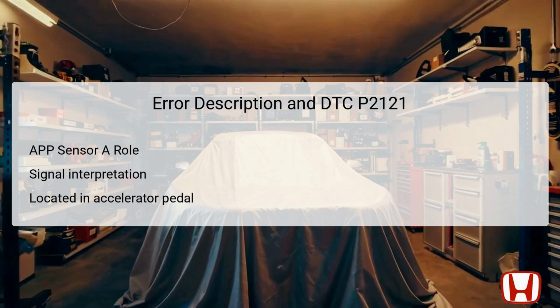The APP sensor A, also known as TP sensor D, plays a vital role in relaying the position of the accelerator pedal to the PCM. This sensor interprets the physical movement of the pedal and transforms it into an electrical signal that is sent to the PCM. The primary function is to ensure the engine's performance aligns with the driver's intended acceleration behavior, allowing for smooth transitions and optimal driving experiences.